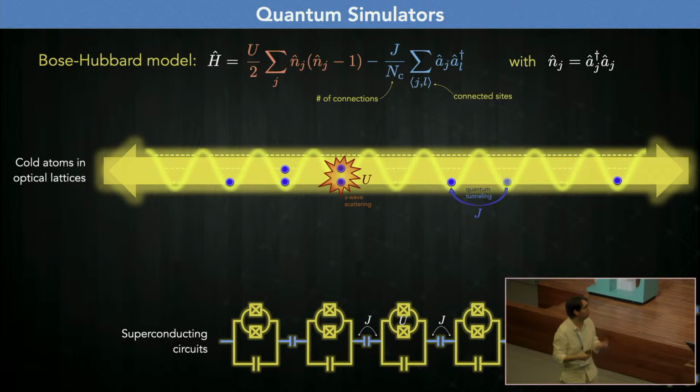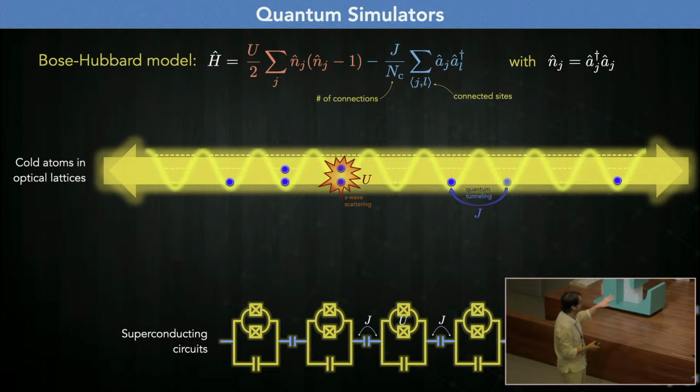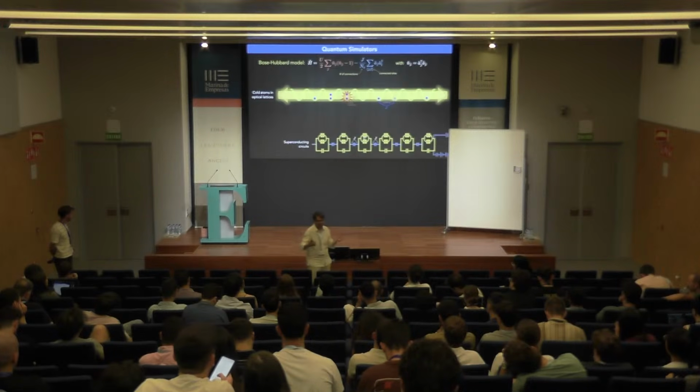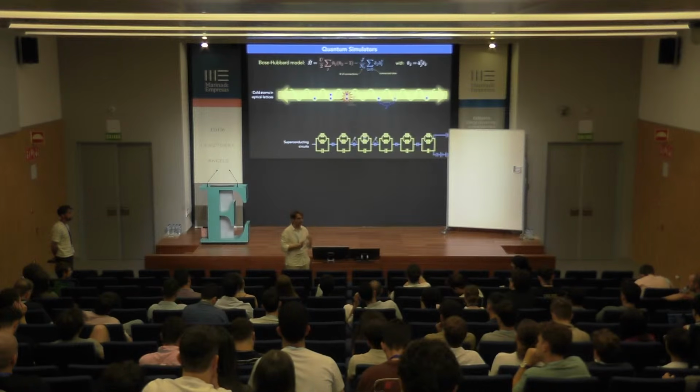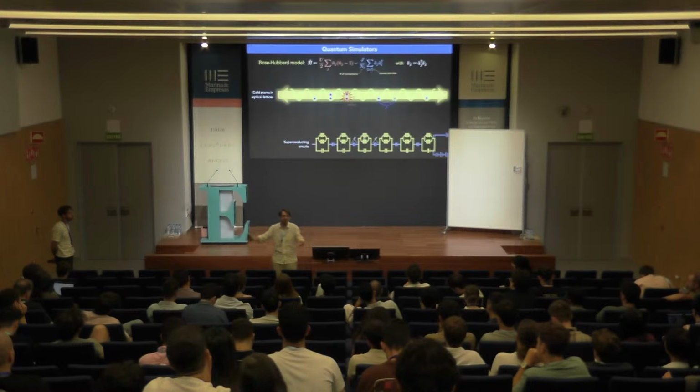But if you want, you can also do something much simpler: take the superconducting cables, allow me the language, and put a capacitor and connect it to a transmission line. That transmission line can be as large as you want. It's an environment like the output of a cavity, an optical cavity. So it's the same. And now the end of that transmission line could be a generator of signals that you can drive the circuit with. But of course, that also creates dissipation. And then you can monitor the system through that transmission line and so on.